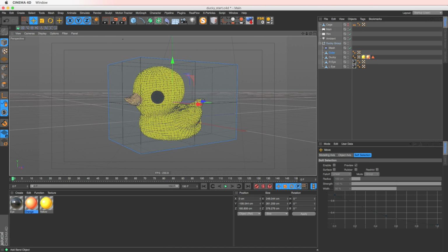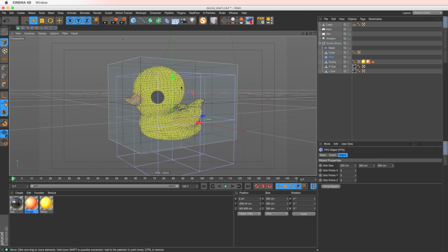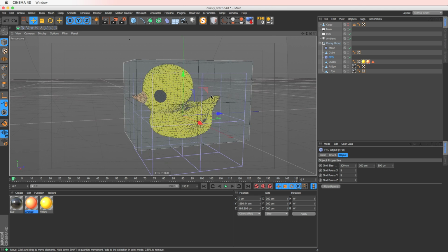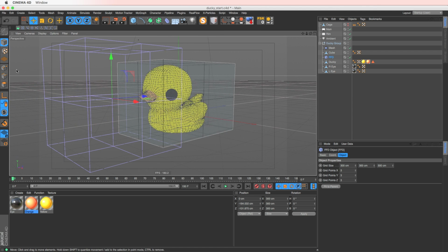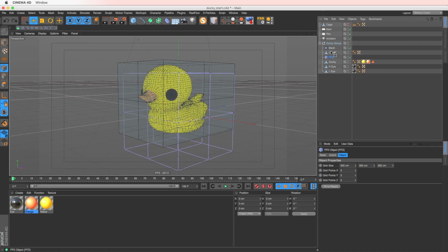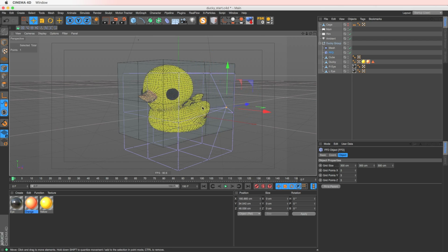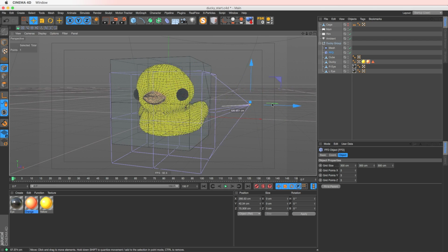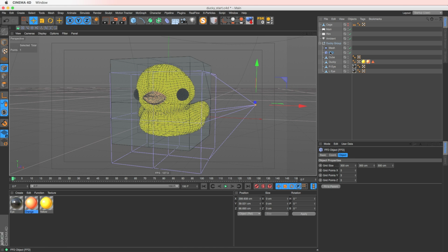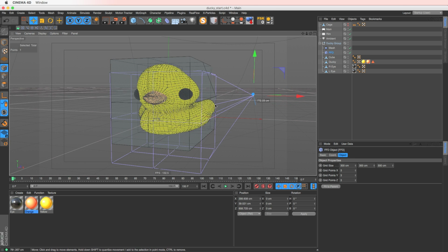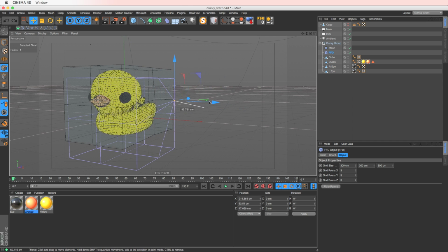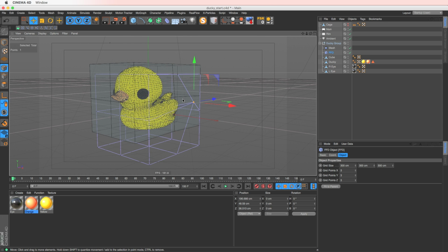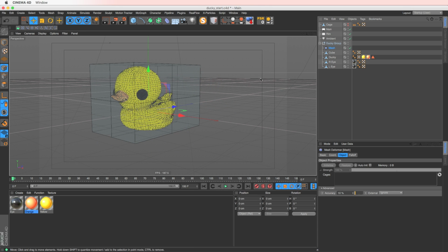Let me bring an FFD object into the scene here. You can basically see this is exactly what we did. It's a cube that we can then use to select points and manipulate these objects or deform the mesh, as you can see that I'm doing now with our FFD deformer in the same level of hierarchy as all of our other objects. Whoop. And that's kind of the basics of that. You're using a cube with whatever grid subdivisions that you want to deform a mesh. Mesh deform works the very same way.